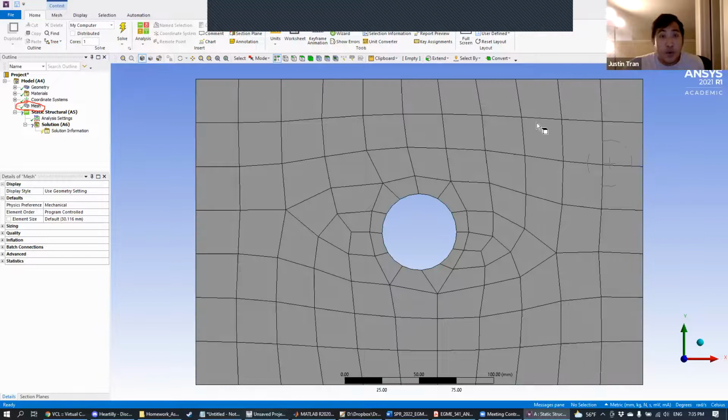Right. And so you can see here that we have a very, very basic mesh on our geometry. And so, you know, we can see here that our big plate with the hole is broken up into a bunch of little squares that kind of litter around the geometry. Okay. And so now this is in a position where we can run a simulation on this because we've discretized the geometry, right? And so we've performed the first step that we need to do in order to produce a finite element simulation. Okay.